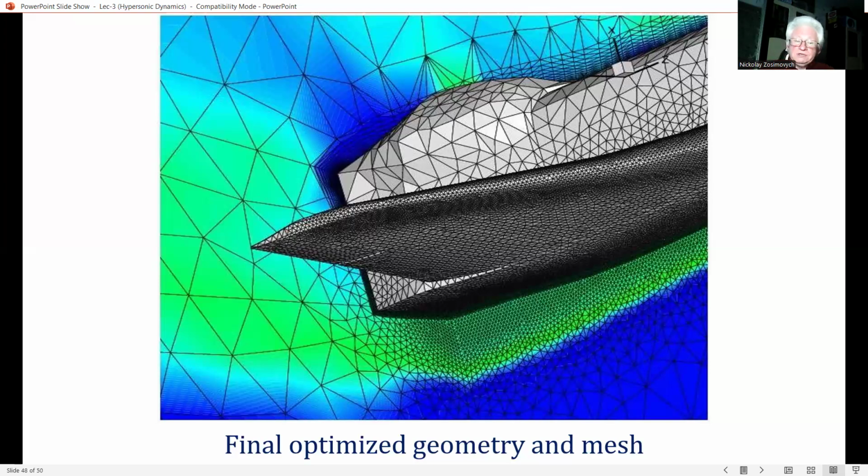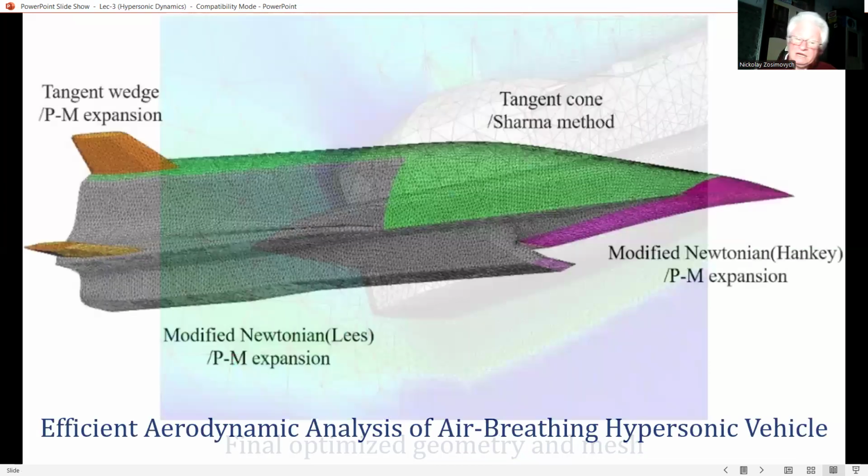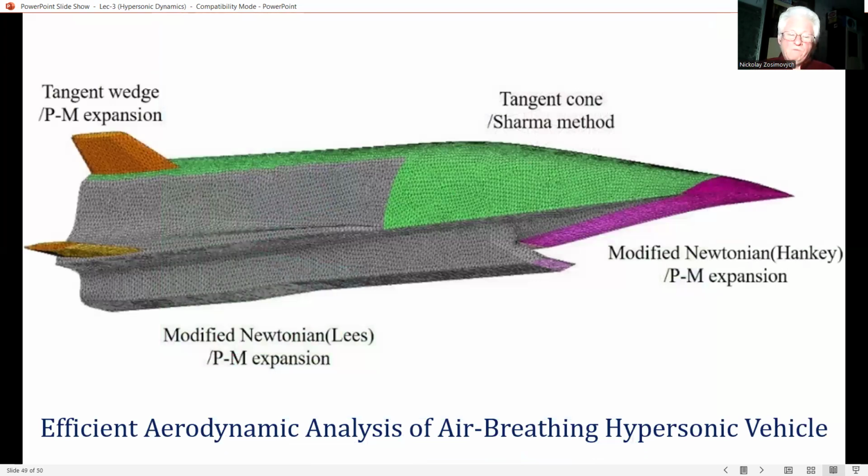He also noted that the fins took on a smooth dihedral shape and were reduced in size. So, in conclusion, the local surface inclination methods discussed in today's lecture, also developed for hypersonic applications in the 1950s, many years ago, are certainly alive and well today.